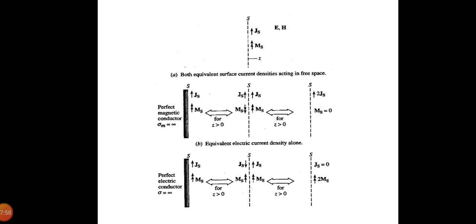Note that if the real antenna contains conducting portions, then Js equals the actual current density over that portion, and the aperture portion contains both Js and Ms before any fixed conductors are introduced. So, if the surface S is large in terms of the wavelength and the curvature of S is small, image theory can be applied locally across the surface to solve for the currents operating in the presence of introduced conductors. However, since the selection of S is for convenience and we are interested in the radiation problem, we can extend S to infinity.